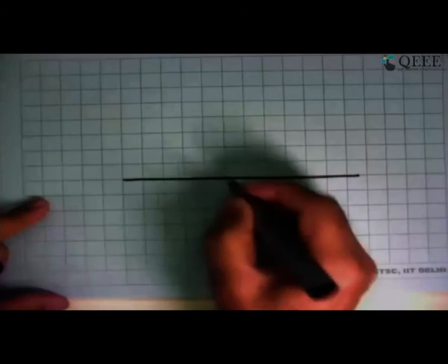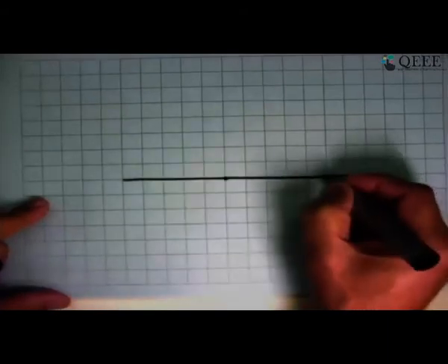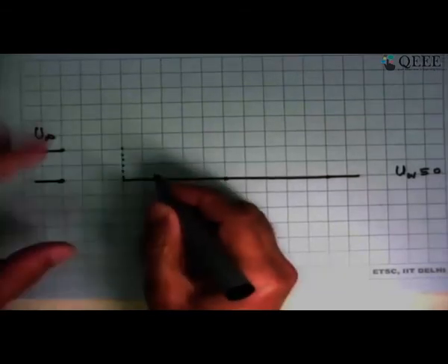the fluid next to it has the same velocity as the wall velocity, which we are assuming it to be 0, and we say that u_w or v_w, this is 0, this is u infinity, and what we learned was that at the leading edge, every element will have the same velocity u infinity.